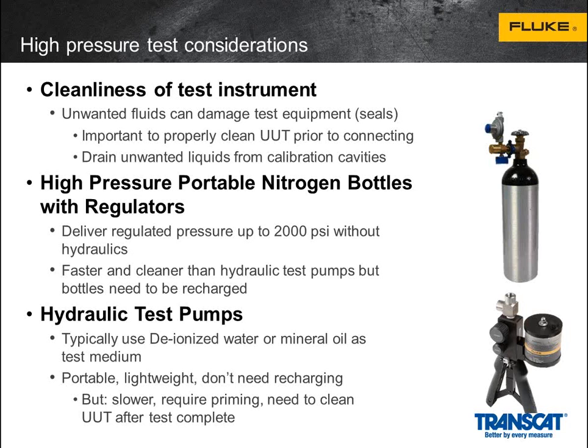The other type of thing that I'd like to talk about very briefly is hydraulic test pumps. Hydraulic test pumps are another way of getting to very high pressures. Many of these hydraulic test pumps can get up to 10,000 psi, assuming you're strong enough to get there. But it's very, very useful in that it's portable, lightweight, and always kind of ready to go, as long as you have the DI water or the mineral oil that you'll need. It does not, however, prevent you from having to clean. You still have to clean up when you're done. It's possible to get mineral oil or water into the unit, and then you'll have to clean it.